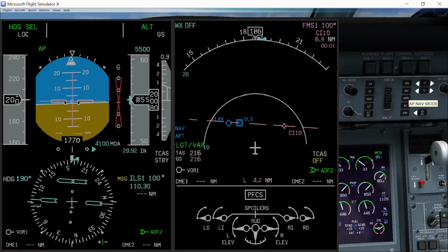Okay, so here we are again. This time what I've done, I have positioned the aircraft slightly closer to the runway, let me put it that way. So it's like after the final approach fix. So again, I'm going to unfreeze the simulator, and then you will appreciate that when you are closer to the runway or you are after the final approach fix, you will be very high on profile, in which case you'll have to definitely abandon the approach because it's very unsafe.